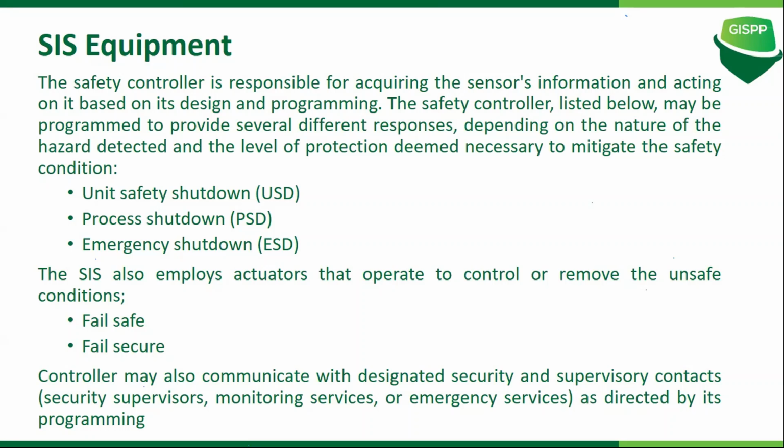They also have a controller feature, so they can send certain data to computers and mobile phones, or place an automated call. They can communicate if anything happens, such as sensor information received that something bad has happened. It will ask the shutdown unit to shut down that process, the entire unit, or the entire plant, and it will be communicated to the team sitting in the monitoring room.